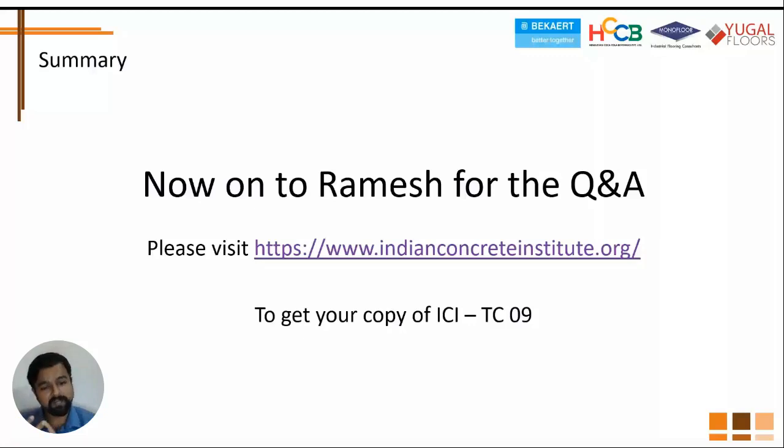That's one. Second, again, will relate to the height of rack that's possible, which is related to surface regularity. If you don't know anything, Tier 34 says build FM2. Which is a reasonable, neither here nor there specification where it's not too tall. So you expect your floors to be somewhere between 8 meter and 13 meter in terms of rack height. So FM2 would work if you don't have a clear idea of who is going to occupy and what is the height of building.